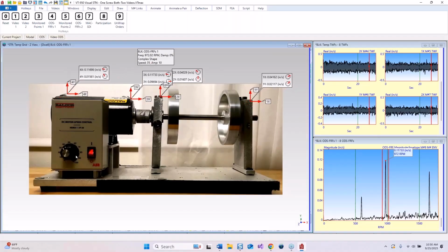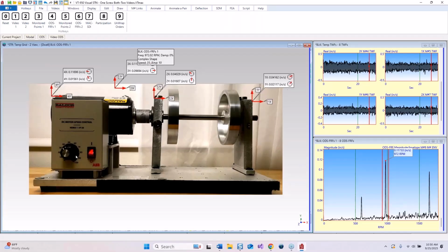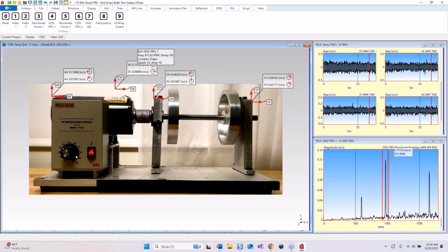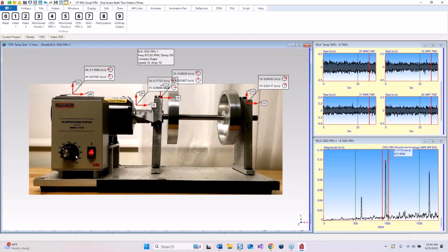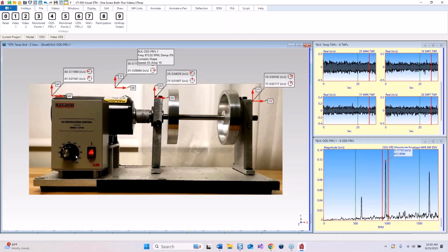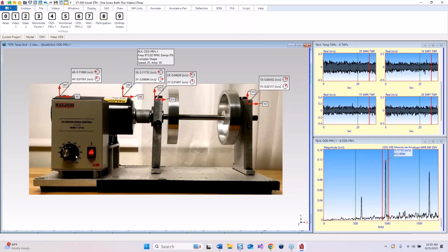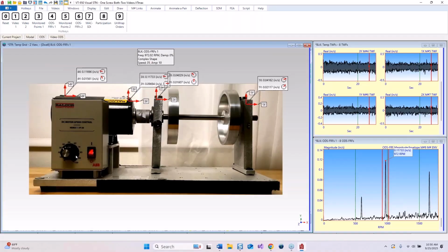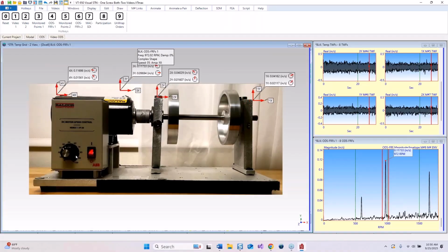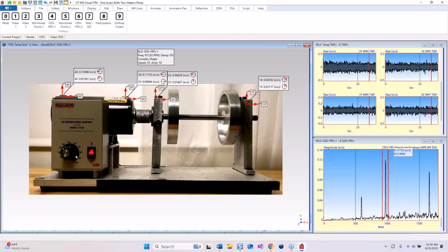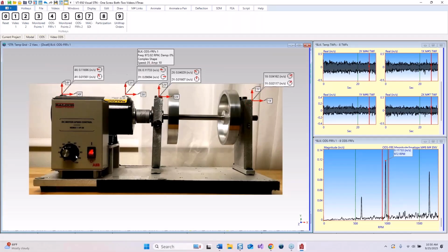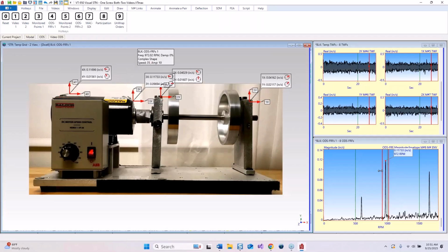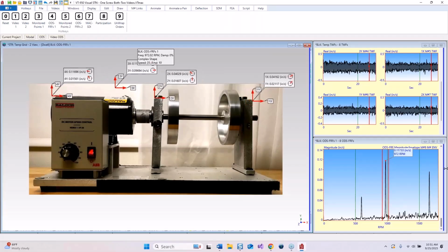Now, when we can't measure the force that causes this vibration, we call it an ODS FRF. If we can measure the force, which we do with an impact hammer or shaker or multiple shakers or multiple impacts, then we call that an FRF. And to get mode shapes, we normally curve fit FRFs, but we have to have the response divided by the force. What we're looking at here are ODS FRFs, and we only have 8 of them.